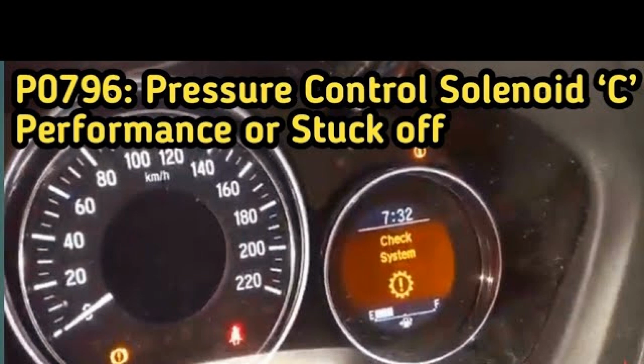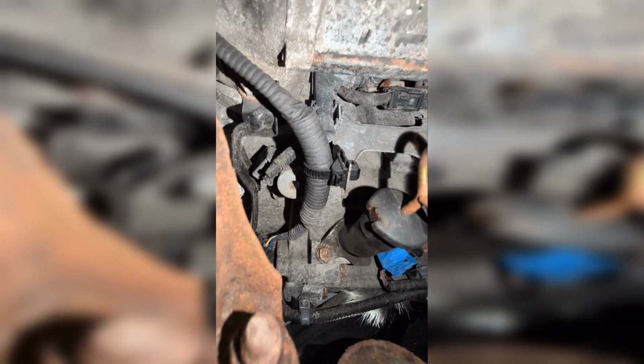Contaminated fluid or clogged gearbox filter. Low transmission fluid level. Transmission fluid passages are blocked. Faulty transmission pump or transmission valve housing. Other mechanical faults inside the transmission. Wiring problem or damaged connector. In rare cases, the PCM malfunctions.